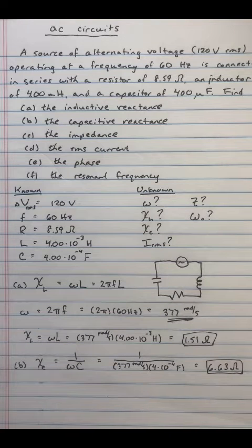Okay, so capacitive and inductive reactances. Okay, I've chosen some numbers that will work out nice and neat for us, of course. That's kind of the point of some of these things. But that gives us a little bit of a flavor of how you're going to calculate it. Also note the units. This is per, so seconds is actually on top if you do this, because it's 1 divided by 1 over seconds. So seconds per farad also yields ohms as units, strangely enough.